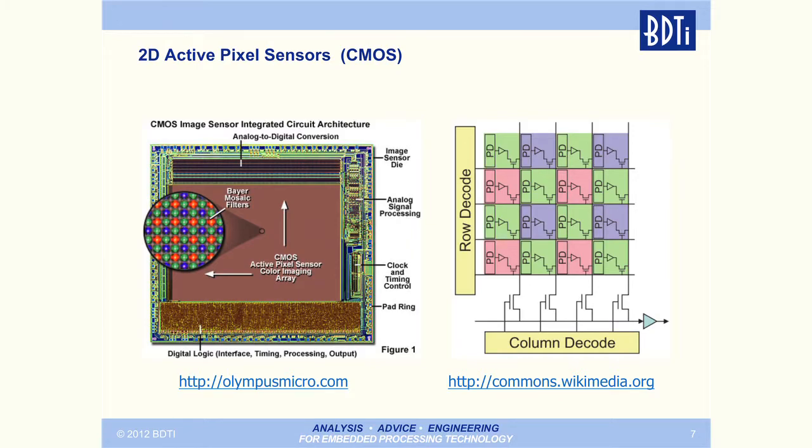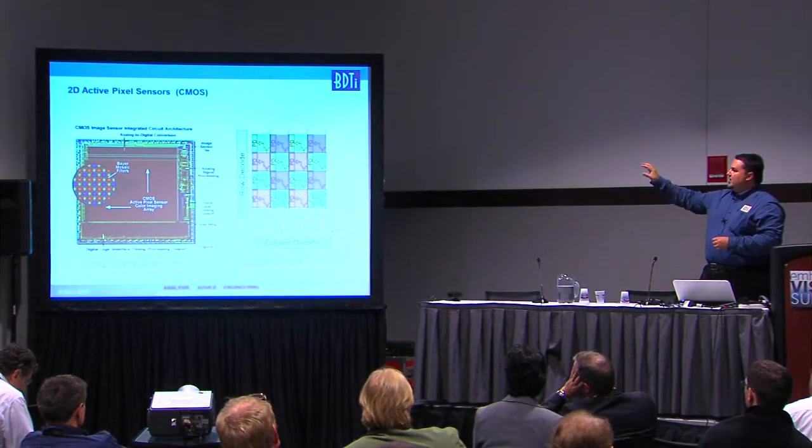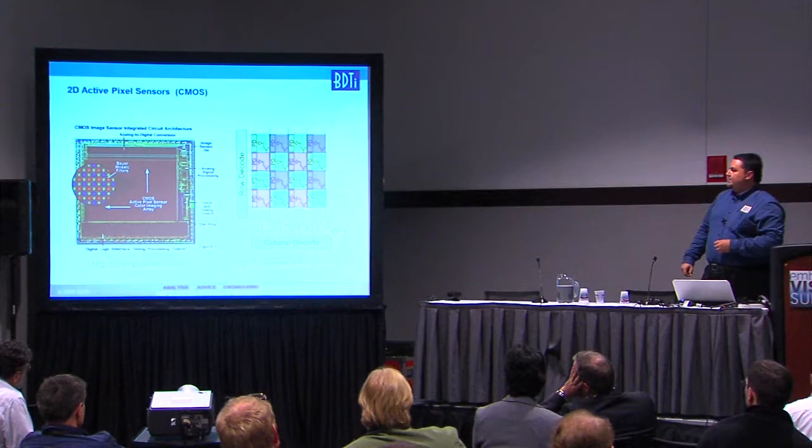So most CMOS sensors, which I'm showing on the left, have an additional ISP. You have the sensor in the center, and then you have something called an image signal processor. Part of the job of the image signal processor is to normalize that image. It's got programmable gains in there that automatically normalize those pixel values.